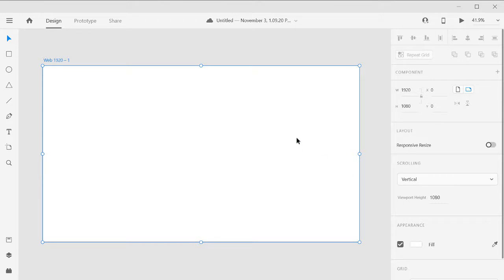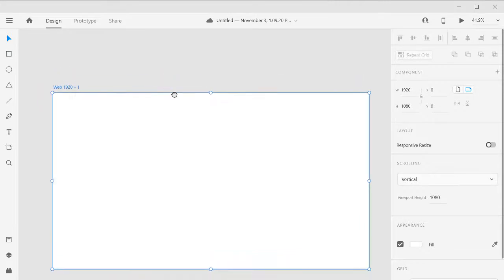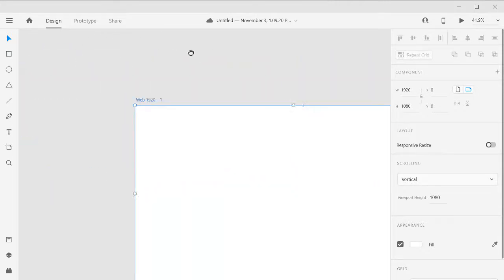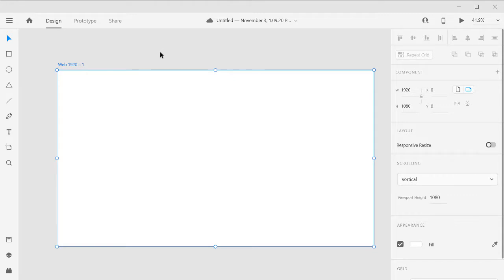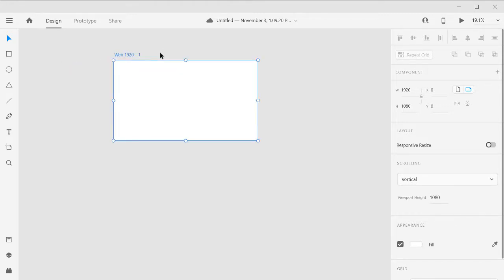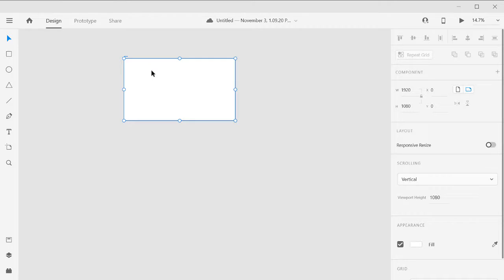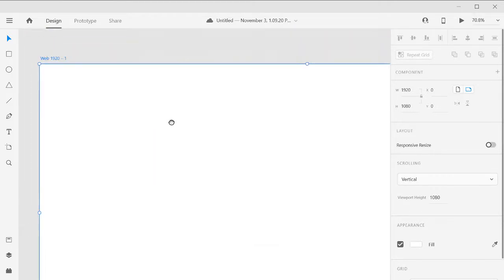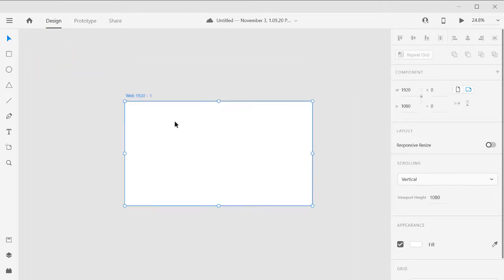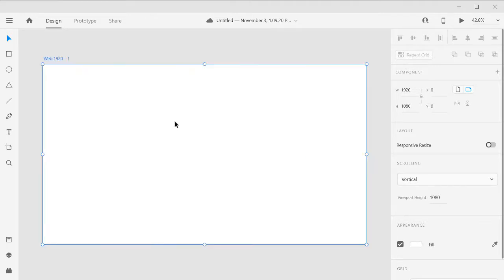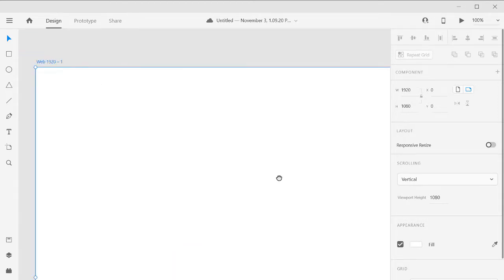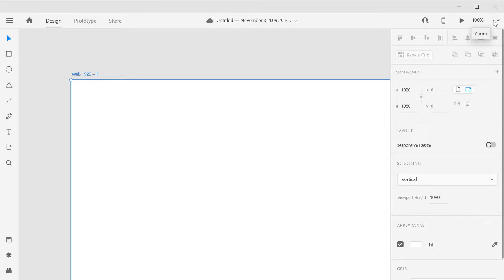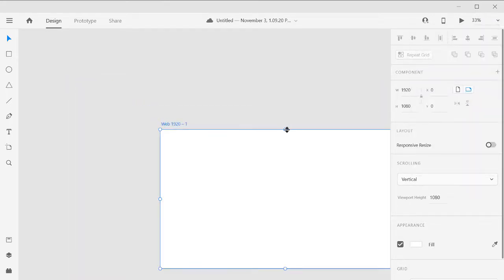And let's start off with navigating. I'm using a mouse with a scroll wheel. So by using the scroll wheel, I can pan the canvas around. And in fact, this is called an artboard, and we can have many of them. If I hit Control and use the scroll wheel, we can zoom in and out. And to quickly zoom, you can press Ctrl-0 to make the current artboard full screen, like so. And then also you can press Ctrl-1 to go to 100%. And we can see up here our zoom setting. It's at 100%. We can also set it this way.